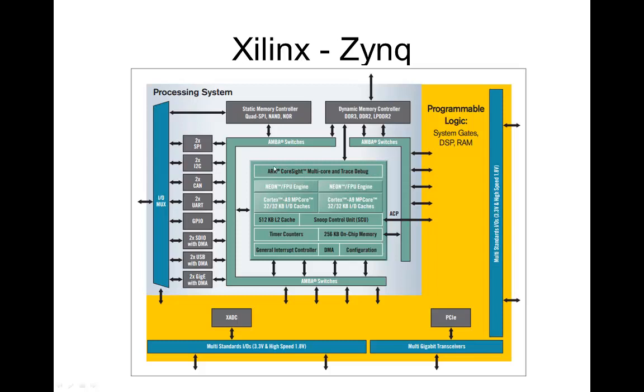So there's an ARM processor with floating point units and an ARM Cortex and cache and memory and timers and on-chip memory and stuff like that. And then it has some other built-in general purpose I/O. And then it's got FPGA fabric around here. All this yellow stuff, I guess, is general purpose I/O. And then they have high-speed gigabit transceivers here for doing high-speed communication. So it's a pretty amazing integration of stuff.